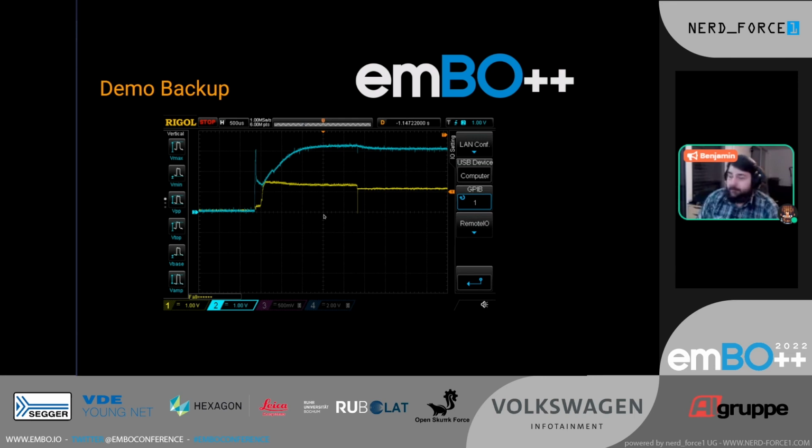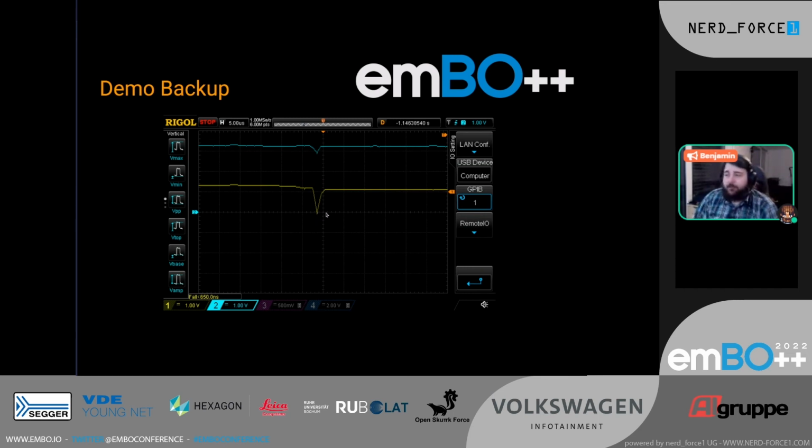and then it continues on in a flat line. And if you zoom in, you can see there's a small V shape, which is because we have capacitors instead of removing the capacitors to have more influence, but it is actually more stable this way. So we drop it, stay there for only a really small time point, and then we let it recover again, and the chip continues along. And note that this is the maximum resolution I could get of my scope. So this is really quick. And this is the reason we are using another embedded device to get the timing right.